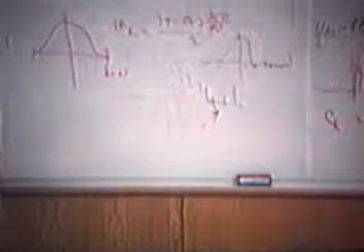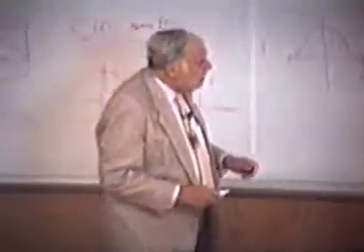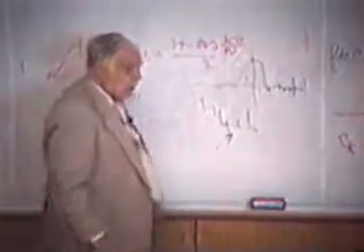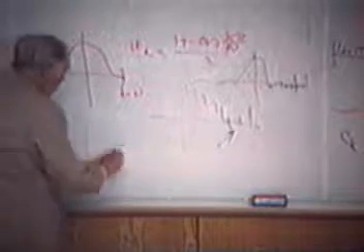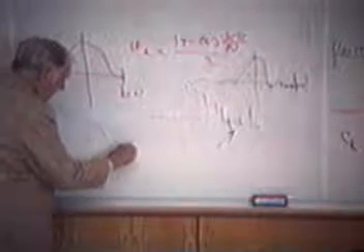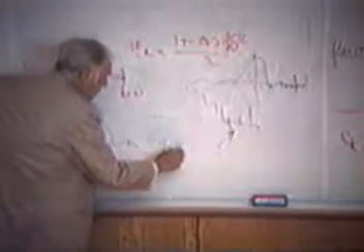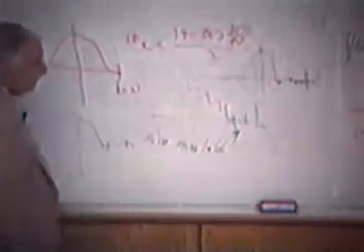Well, we were working in a field where there was a very strong line over there, like 60 cycle, but it wasn't. It was another strong line. In which case, if that strong line were over here and leaking through one of the side ones, it would dominate what we're looking at. So Tukey asked the question, what kind of a window will have the minimum max lobe? How can I keep the max down?